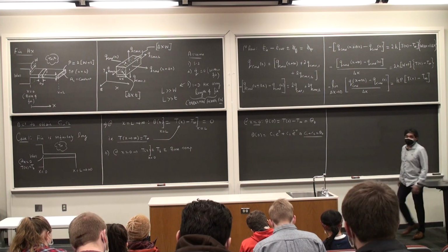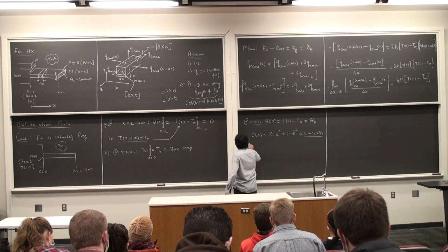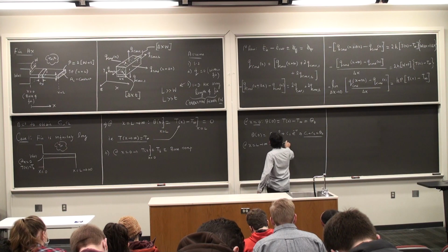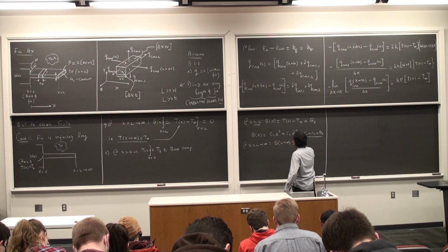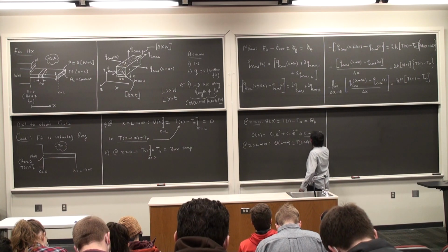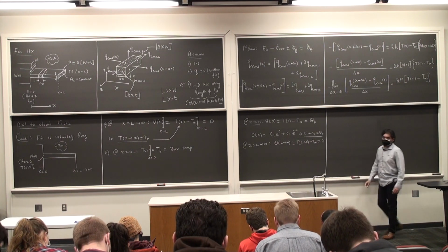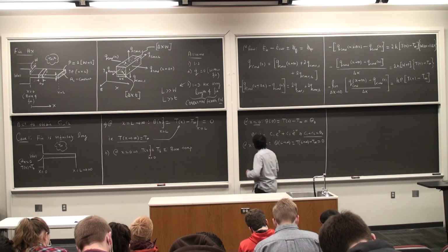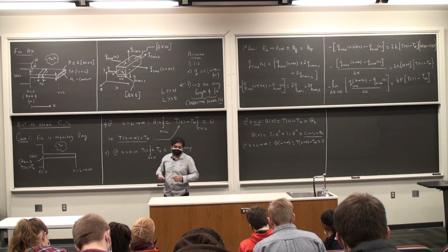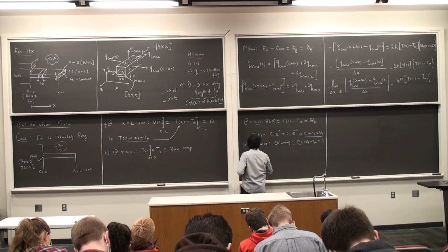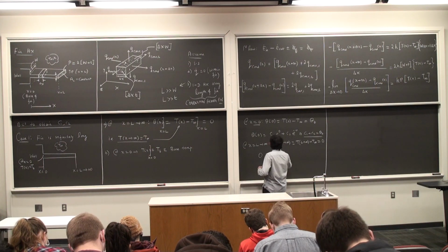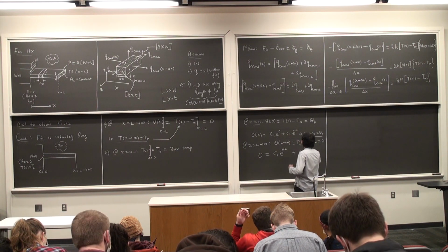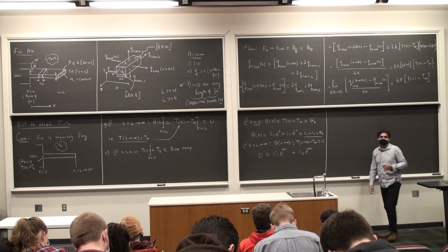Then as x tends to infinity, at x is equal to L, theta is T at L tending to infinity minus T infinity. This is 0. I'm taking this and substituting it back into my solution, which I had written down somewhere in the previous panel, if you have been taking down these things. This is going to be 0 is C1 e to the power mL plus C2 e to the power minus mL, and now we are stuck.